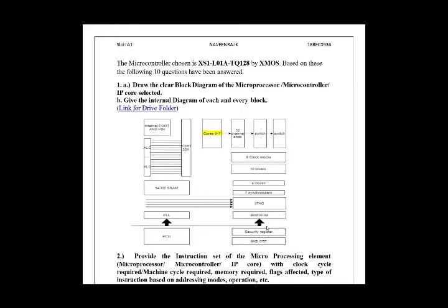So talking about the PCU, it can be used to isolate the core voltage of the device and reapply it under a controlled condition known as sleep mode. In sleep mode, all data in the SRAM is lost. SRAM doesn't store any data in sleep mode. Okay, so the device recovers into functional mode under the control of an external signal. This signal is called the PCU wake signal, or an internal timer. Okay, so this data is recovered using this signal.